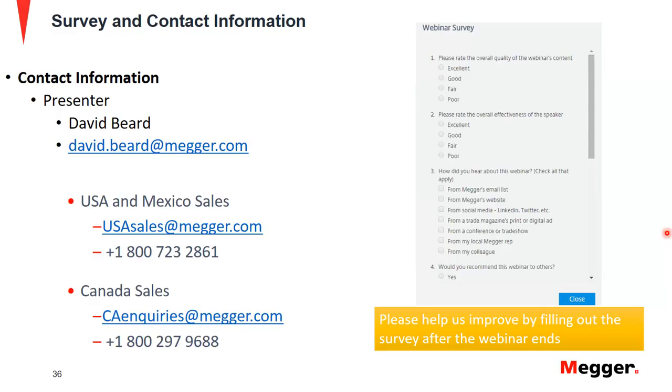Oh, thank you. Yeah. So yes, we can absolutely test a breaker trip unit with the relay test set. We have a feature of recording time on our home screen, so anybody can use a pre-fault to fault home screen, provide nominal values on pre-fault, and then pick up values for the breaker trip on the fault state. And all they need is a way to connect to the binary input of the test set.